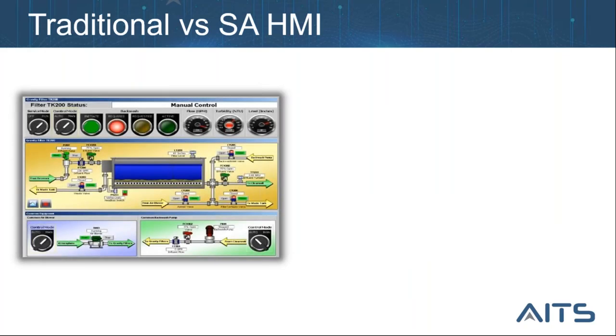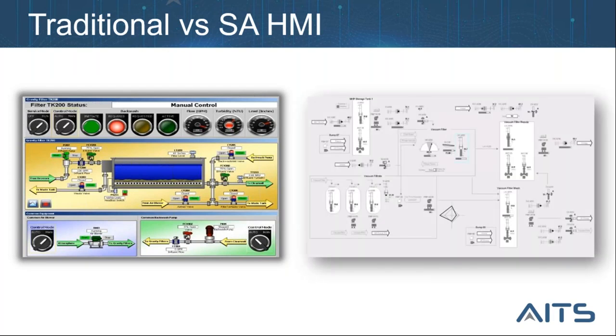Now, I will show you how HMI has improved by following the situational awareness standard. If you were using the traditional HMI, you are familiar with the typical problems, such as the poor presentation and interaction with alarms, lack of built-in standardization, inconsistent colors, 3D effects, and animations. The implementation of situational awareness enhanced HMI in a way that colors are rationalized, the design is user-centered, and as you can see, alarms are integrated.